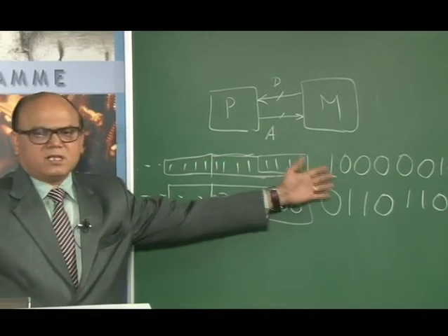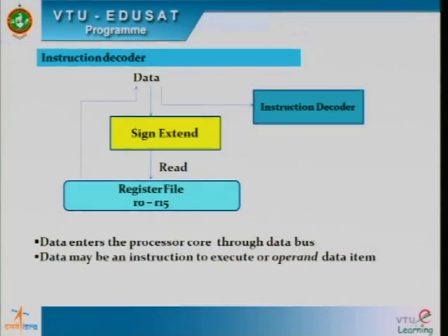So total word size is 4 bytes, that is 32-bit data. So being 32-bit data, if the data received is 8-bit data, then the sign extension unit will appropriately pad zeros or ones into the remaining higher byte positions. That is what is done by this circuit.